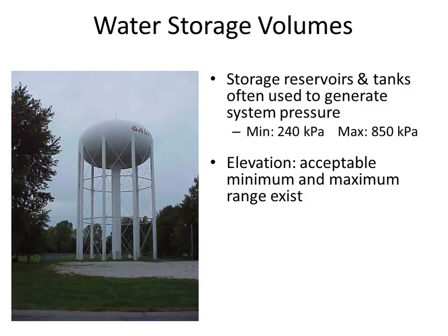So remember that what you have done so far with the reservoir is you've taken a look at what sort of pressures are going to result in the system on account of the elevation that the reservoir is placed at. You want to have the reservoir as high up on the hill as possible because that's going to enable you to use smaller pipes. A smaller pipe will yield more head loss, but if the reservoir is high up on the hill, then that pressurizes the network as much as possible, and it makes the head losses less worrisome.